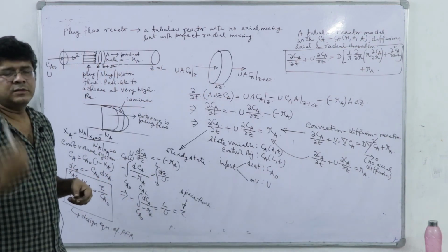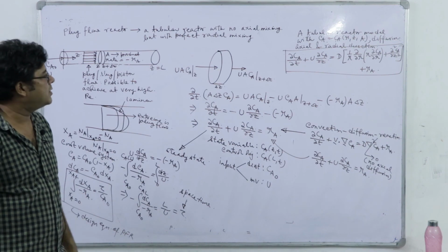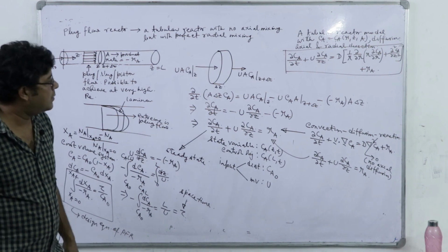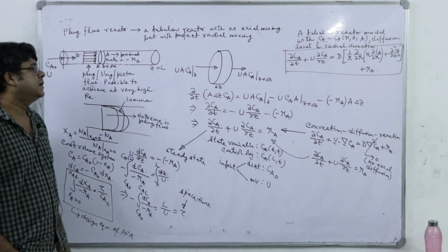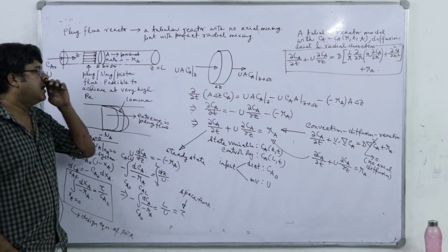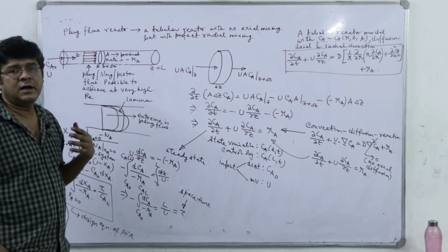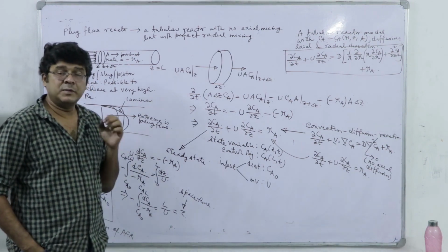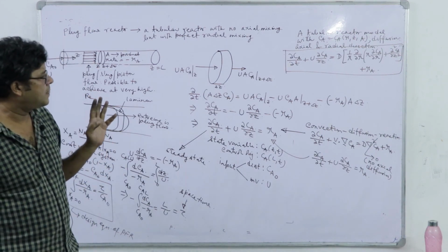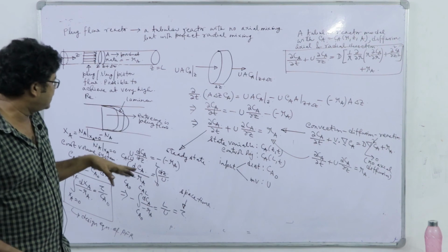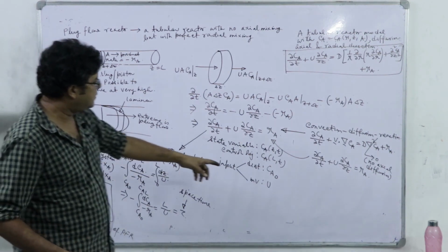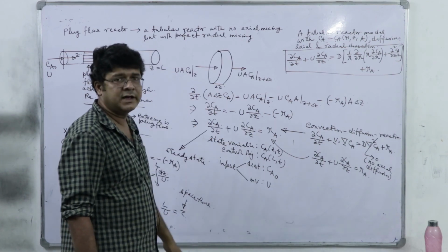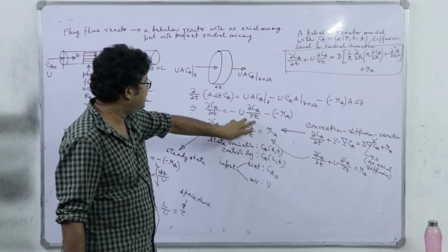So that is all about the lumped parameter model and distributed parameter model, the overall modeling approach. We have formulated the state model, and the state models are to be solved in order to generate the input-output model. But the problem is, if I consider u to be a manipulated variable, u is grouped with a derivative of the state variable, so this is typically a nonlinear term.